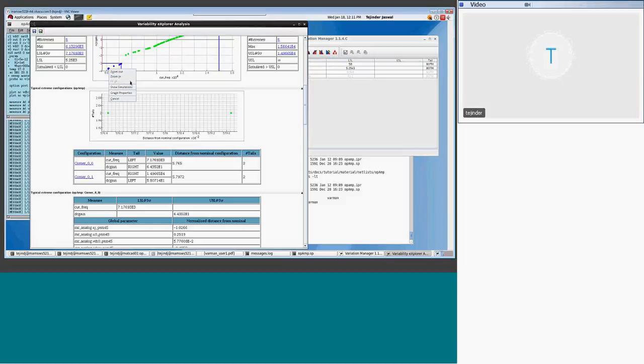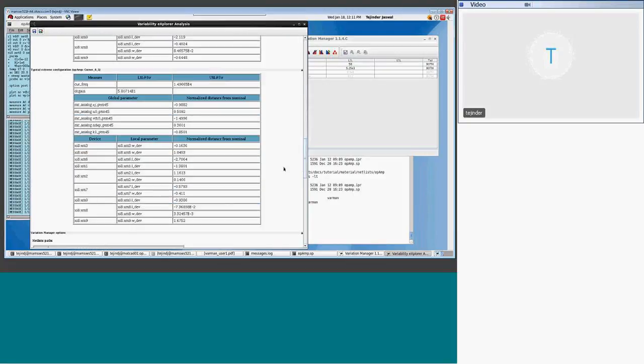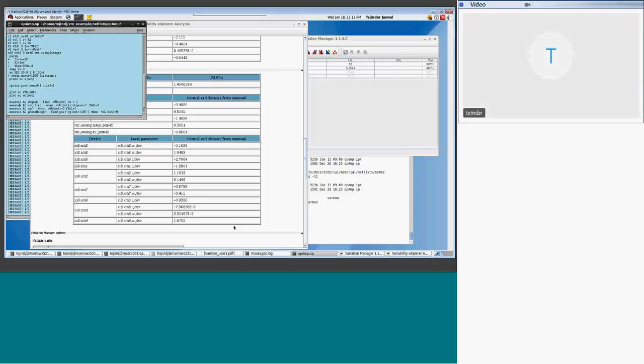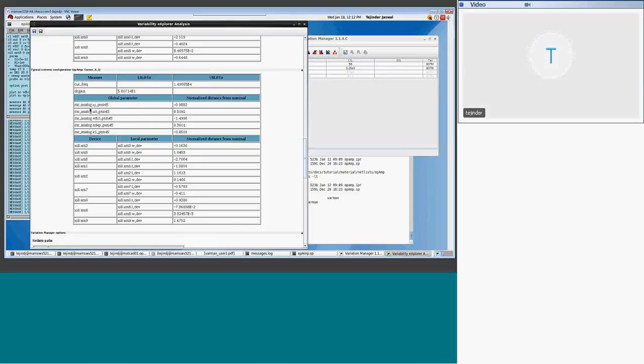For the full model, say for the transistor, it's just adjusting the length and width. But if this model has Monte Carlo local parameters, other local parameters, they would show up in that list, right? In other words, length and width are the only things in the model. Probably this is just a simple model. Yeah, if you look at that, you have XJ and mobility and VT.